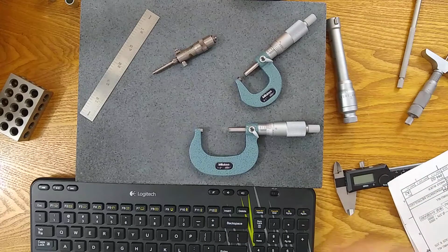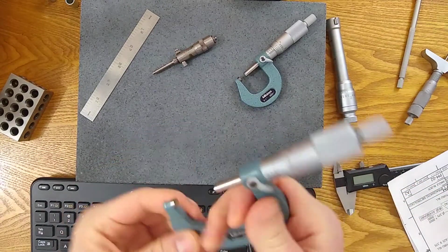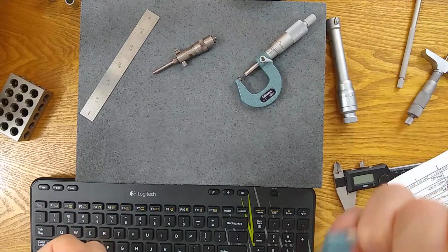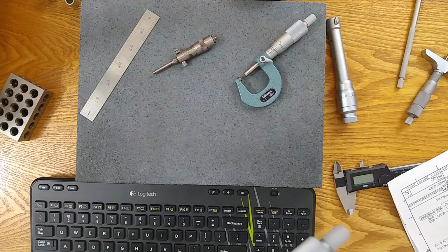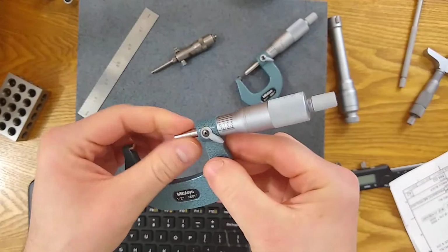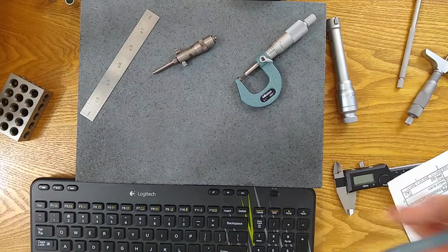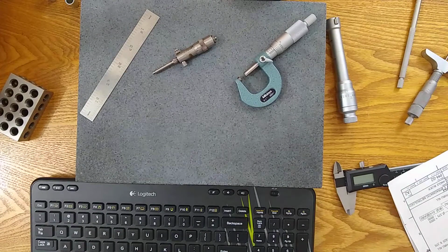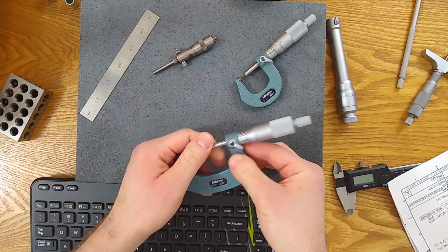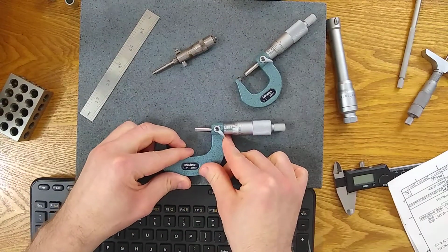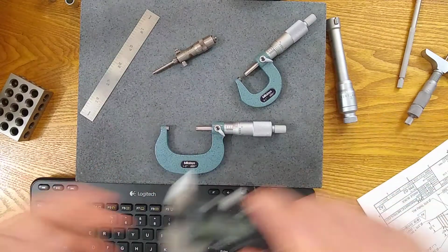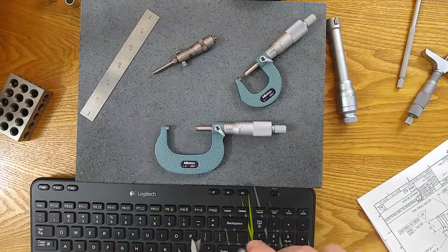So sometimes you maybe picked a gauge like a micrometer that is very accurate but may be overkill. You thought, yeah, I've got to use the micrometer. I want the accuracy. And then it takes a little bit longer to use and read micrometers. Not a whole lot, I mean, it's debatable. I've had a number of people say to me, yeah, I'd rather use a micrometer than a caliper. And that's personal preference. I'm not going to argue with that. But generally speaking, calipers will be faster, easier, with more variety of features it can do.